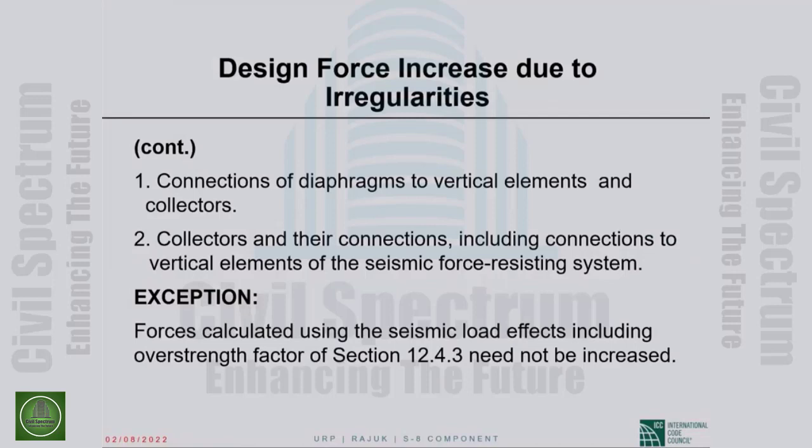So, let me, the very nice picture. This was in the previous segment. Do you remember the picture of the diaphragm that I showed to explain what collectors are? So the diaphragm is connected to the collector where there is no shear wall. The diaphragm is connected to the shear wall where there is a shear wall.